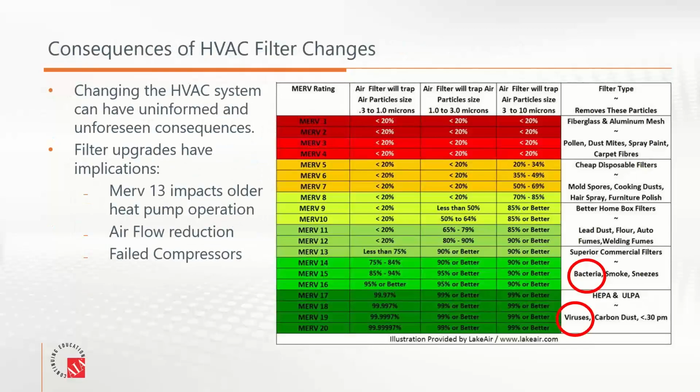A question that we frequently get, and one that was posed here, relates to UV, and there's been so much discussion about installing ultraviolet lights. This person is asking, why not just install UV lights only in the duct streams? Well, first of all, it would be extremely expensive. The light cost is very expensive and people don't realize it. Plus, it's a high electric energy user.